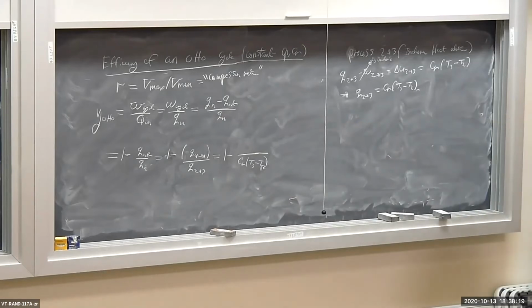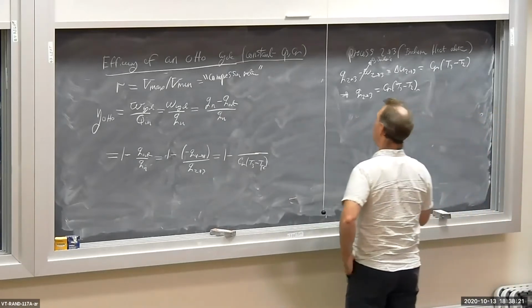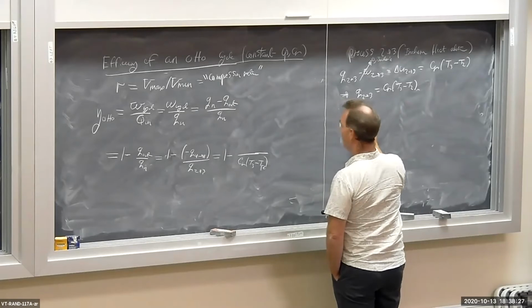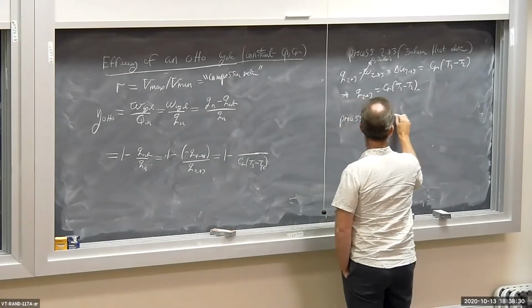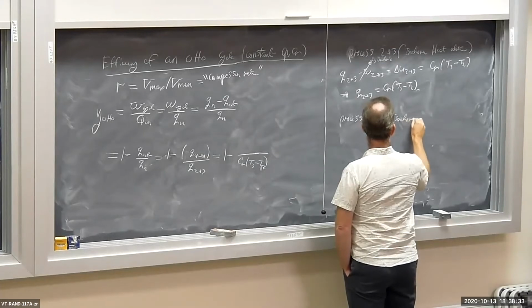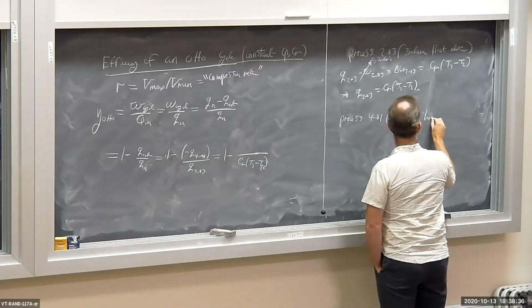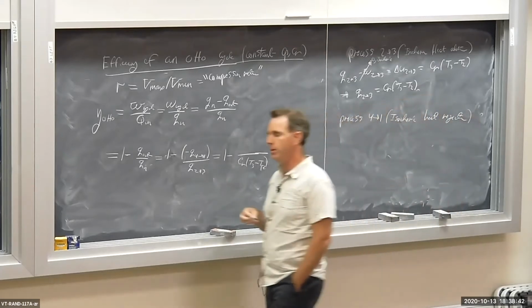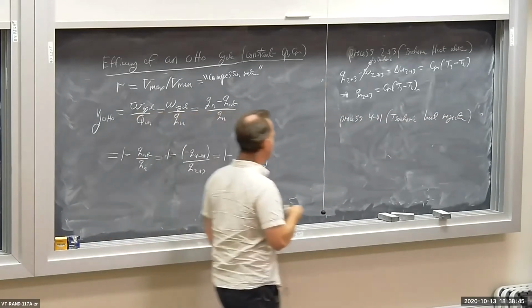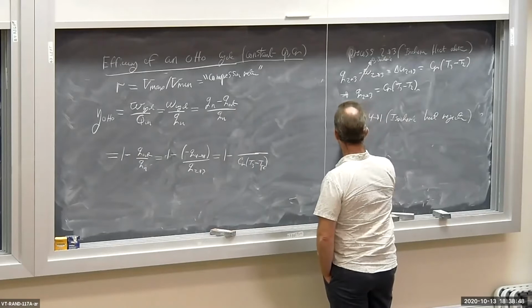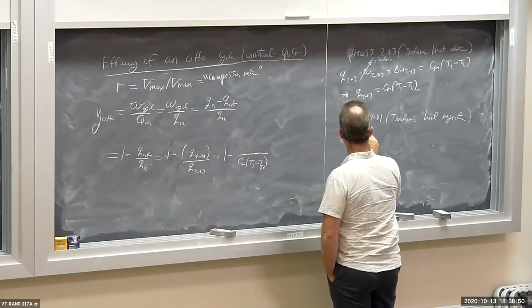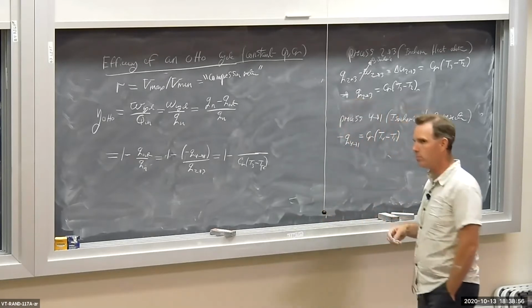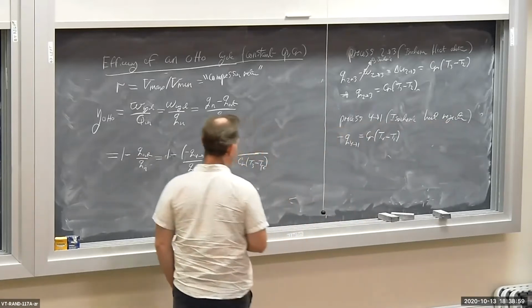You go through and calculate the heat rejection, and you get the same thing. So process 4 to 1 is isochoric heat rejection. And I find that negative q 4 to 1 is equal to Cv times T4 minus T1.